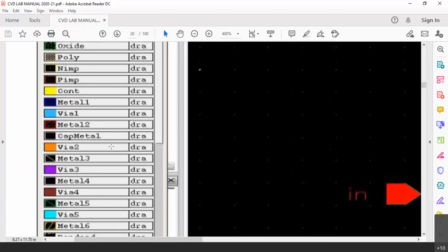So please recall the discussions of the theory class, where you have a process called metallization, and there are many procedures for metallization itself, such as sputtering or anodization. By means of metallization, metal tracks are created on the surface of the chip, and using these metals all the devices are connected together.